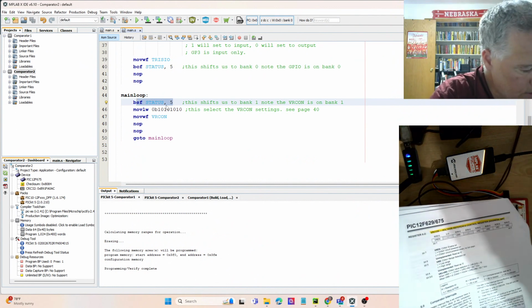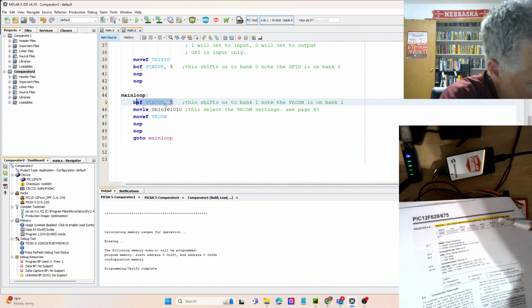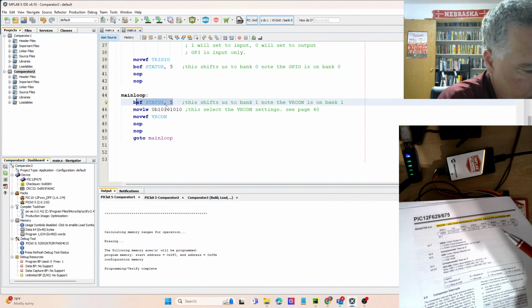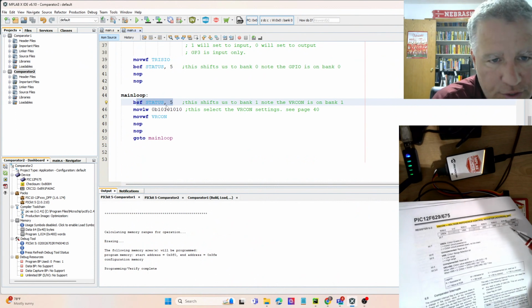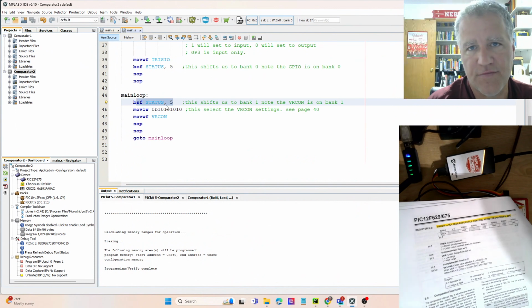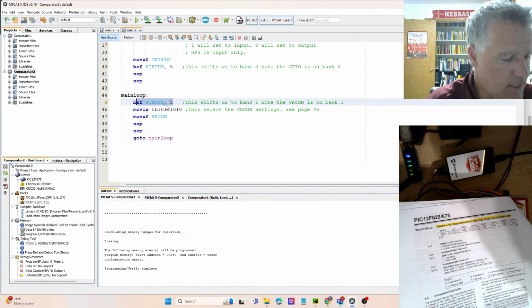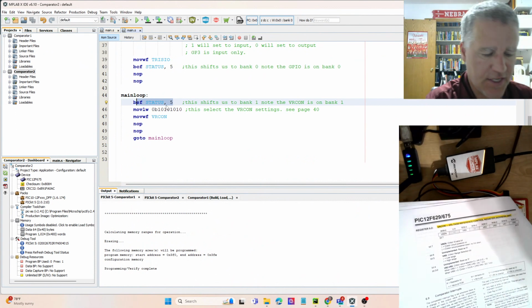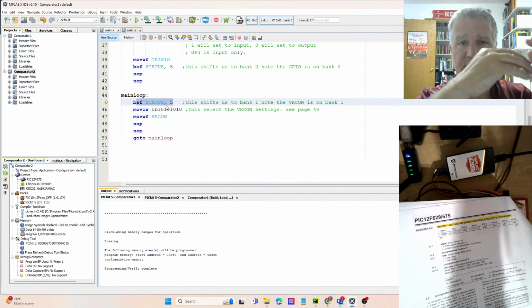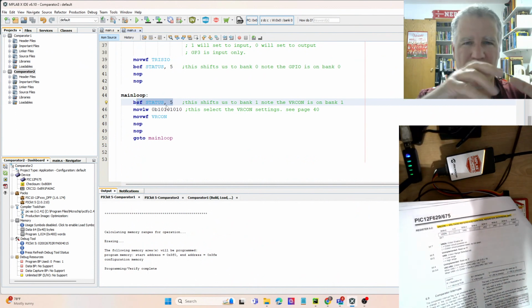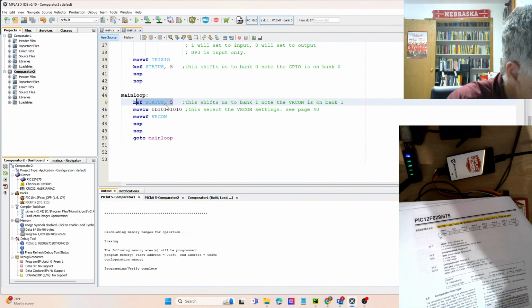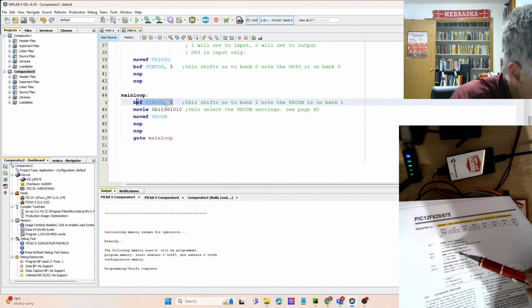So what we're going to do here is tell with ones and zeros what voltage we want as basically a percent of the voltage supply. In order to give more range on that, you set it to either a high voltage, something above about half, or a low voltage, something below about half. We're going to go ahead and use the low range.